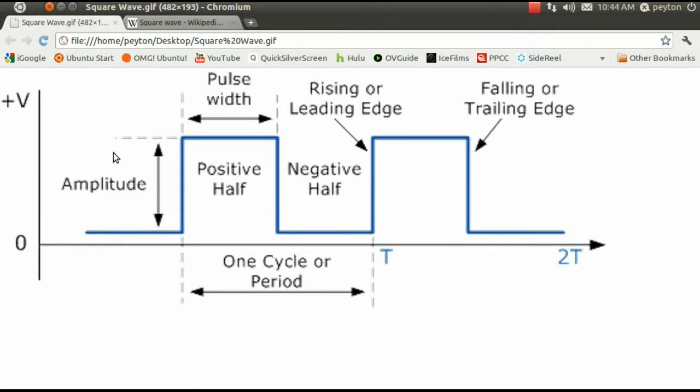A square wave is a kind of non-sinusoidal waveform which is universally encountered in digital switching circuits and is naturally generated by binary logic devices. In this square wave, we are alternating between approximately 0 volts and some positive voltage. Since our Arduino Uno is hooked up to the USB port, we'll also be using 5 volts.